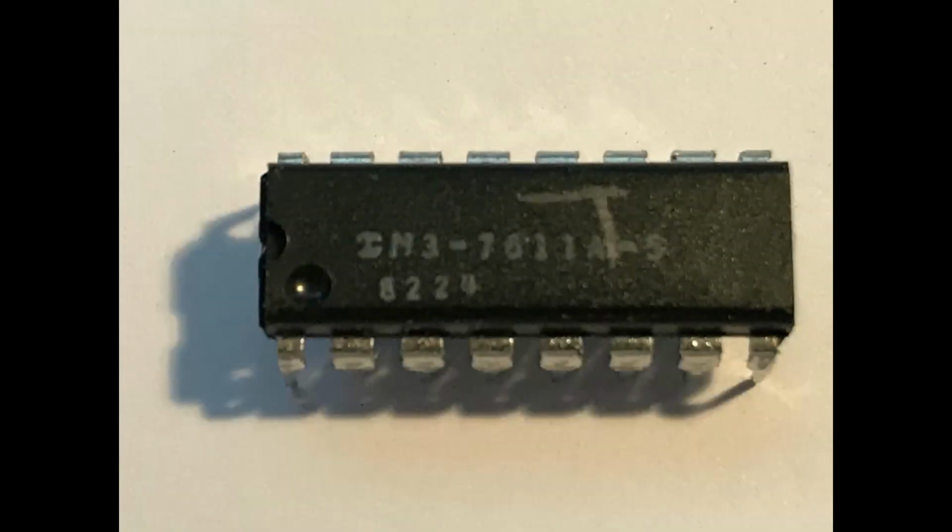The color PROM. This chip is a bipolar programmable read-only memory chip. I've put a datasheet on the GitHub for reference. It's a small 16-pin chip of 256 bits by 4 bits that is used for color palettes in many of the early arcade games. The beauty of this setup is that the color palette could be interchanged by just using different PROM chips. I think that these chips are quite fast in their operation since they need to be working at 6 MHz to get the color info on the pins.